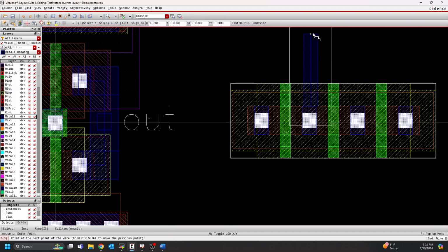But if we have a route going up into here, and then this side is going down, this other side is going down. If this is our VDD net, this top one is our VDD net for an NMOS. So if this is our ground net here, then we can see we have one transistor that has its own independent drain, goes through the gate to ground. The second one also has its own independent drain, can go through this gate to ground. So in a similar fashion, we could potentially add a ground connection here, and that would create 2 transistors in parallel.